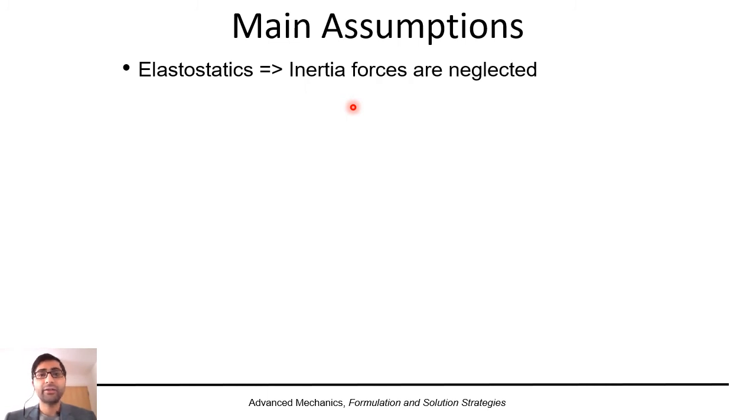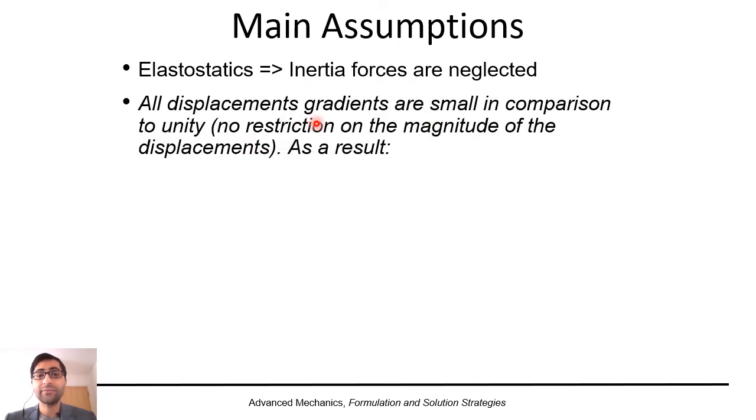Then here are the main assumptions for problems that we deal with based on elastostatics. First, inertial forces are neglected. So we don't care about acceleration terms. All displacement gradients are small in comparison to unity. Note that we're talking about displacement gradients. But there is no restriction on the magnitude of displacement.